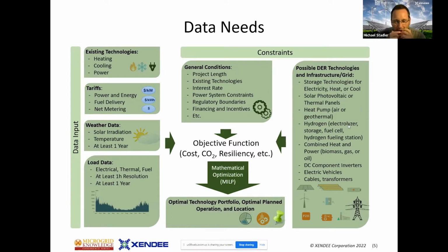I mean, I already had a couple of questions around this. What data is really needed here? And I would say the most important data is actually the load profile. And you just don't want to have an average load for the full year. You really want to have at a minimum 8,760 time steps so that you can model load shifting and all that stuff, and that technologies can respond to different electricity rates, which are often in combination with higher demands, really important here. So load profiles are really important. We have databases in Xendee helping you on this, but the more details you have on the load profiles, the better it is.